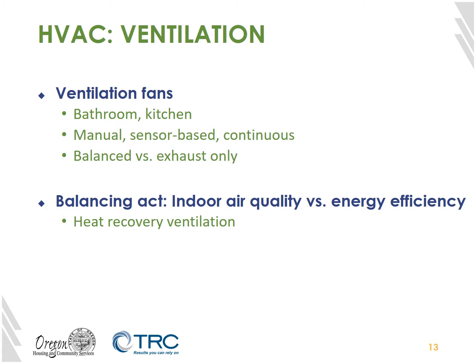Ventilation is also crucial to take into consideration. Existing ventilation may not be present at all or may exist as manual fans in bathrooms and kitchens only. This program incentivizes bathroom fans with humidistats to control how frequently they run. To improve indoor health, a balanced ventilation system is recommended. This involves adding supply fans so that both incoming and outgoing air are controlled. This prevents air from becoming stagnant inside of the building or being dragged in from uncontrolled areas via a depressurized building caused by outgoing fans only.